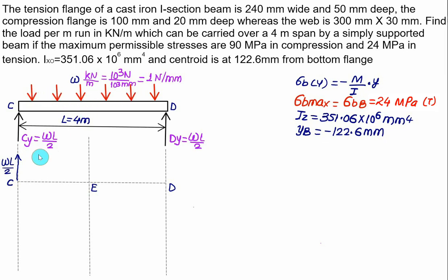So if the load is rectangular, you will get a triangle in the SFD. So this total vertical distance is WL, and therefore we are left here with minus WL by 2. So we have WL by 2, but a negative value, and the reaction at D is the same as WL by 2. So finally we'll close at D equal to 0. This length is equal to L by 2, that is 2 meter, and this length is also L by 2, equal to 2 meter. So the area of the SFD will represent here the change in the bending moment diagram, and the area of this triangle is equal to 1 by 2 times WL by 2 into L by 2.